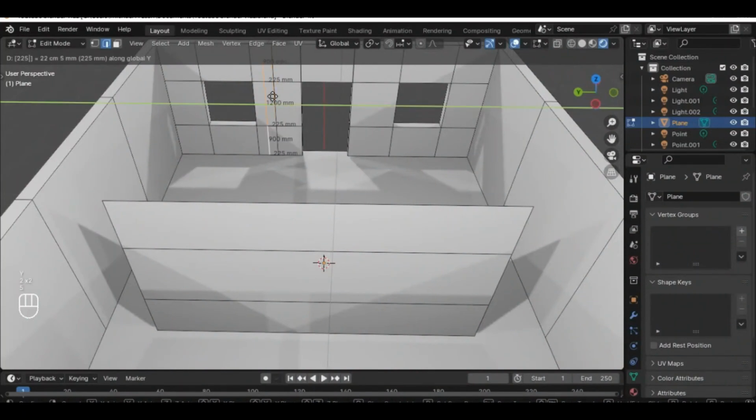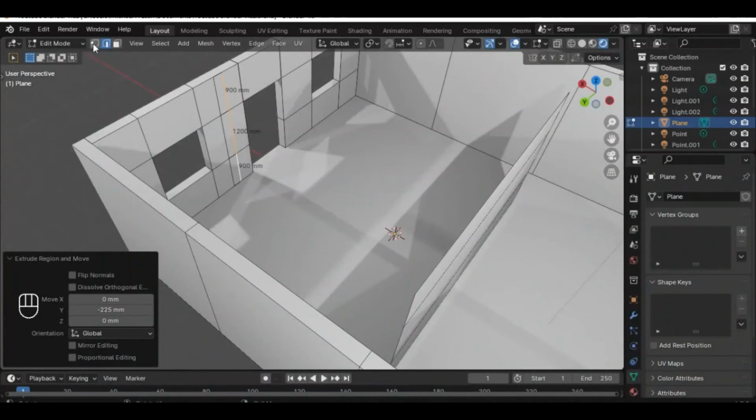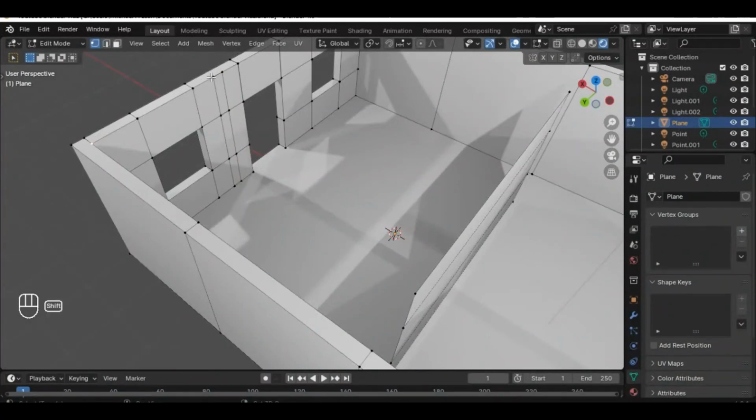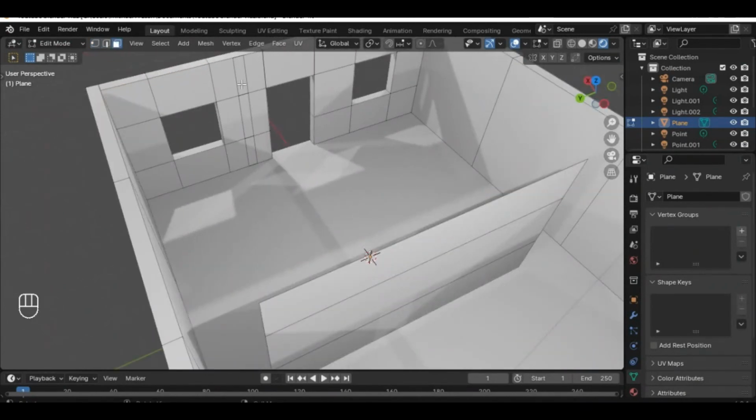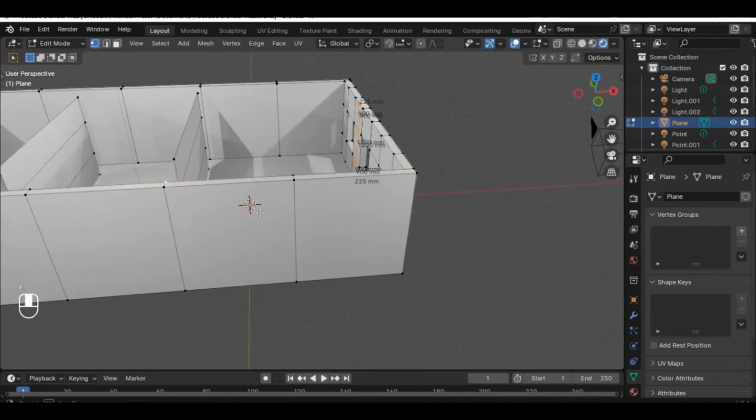So I want to create a wall here. Let's see if these things are connected. This is very important to check if they are connected. So now I can extrude towards the Y direction 225 with my wall. I want the in-to-in dimension of this one to be something like 2561, even though that's a very small room, but it should do.